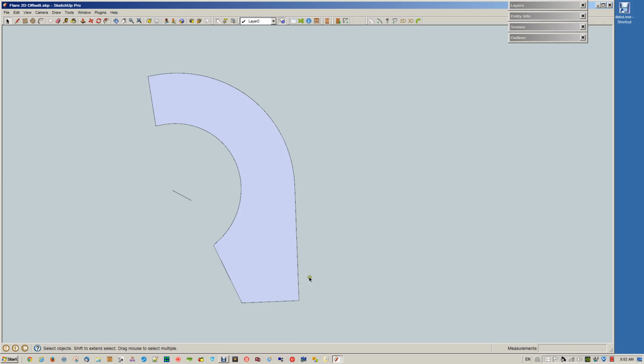So let's start with the offset. Now for our stringer, we're going to use a 60 millimeter stringer wide on the inside and a 54 on the outside. The reason for that is what I generally do building stringers is I'm going to use 5 layers of 3/8 spruce and 2 layers of 1/4 inch finished plywood, good one side like oak or whatever on the inside, both sides, but only one side, only on the inside of the outside stringer. So that being said, let's look at an offset.